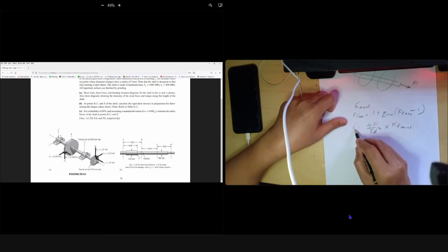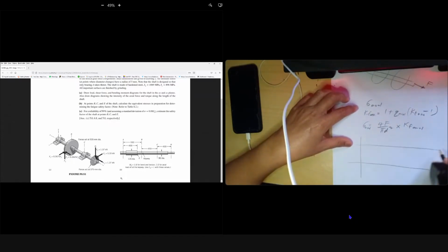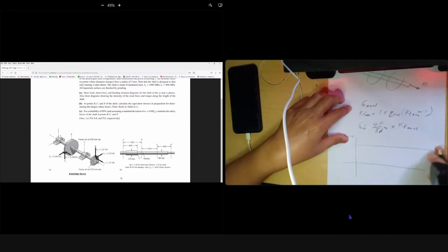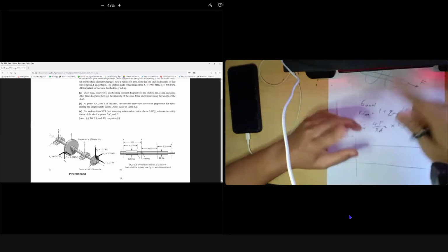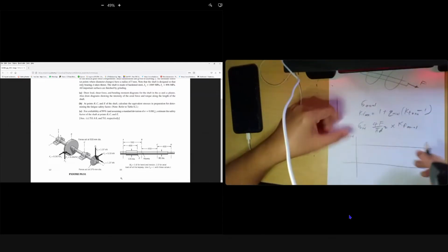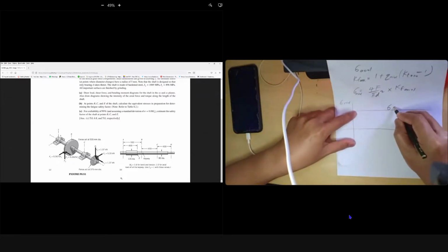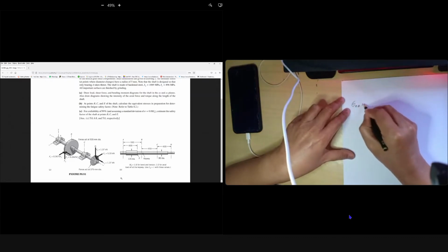So this is your sigma axial, because I said axial along the shaft remains the same. Sigma axial with time is a constant line, remaining the same even when the shaft is rotating. Unless bending, which is completely reversed, with tension at the top and compression at the bottom. Torsion is the same, a constant line. So for axial we only have sigma mean; sigma A is 0.